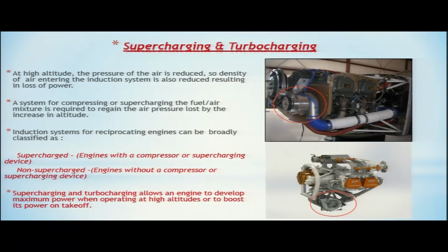So, a system is required for compressing or supercharging the fuel air mixture to regain the air pressure lost by the increase in altitude. Whatever power we have lost by the increase in altitude, we need to get that power back. So, we need a system which will compress or supercharge the fuel air mixture so that your density is not reduced and your power is not lost.